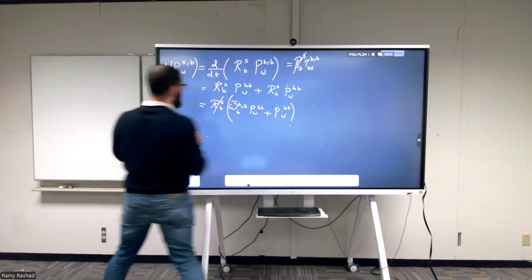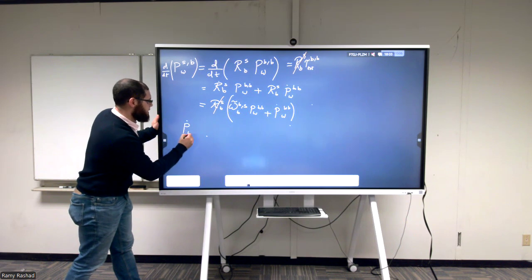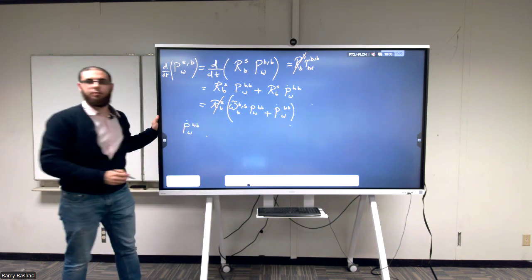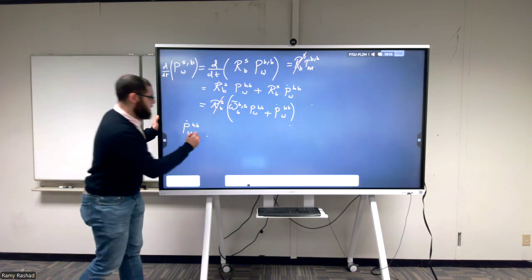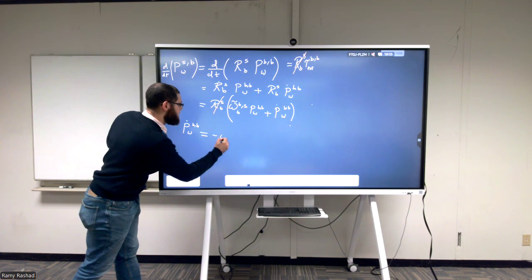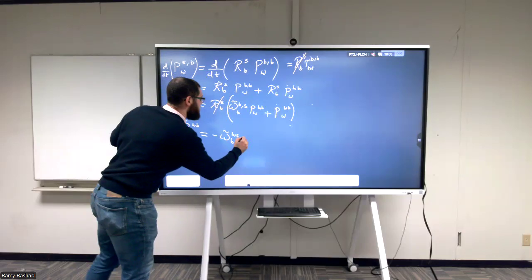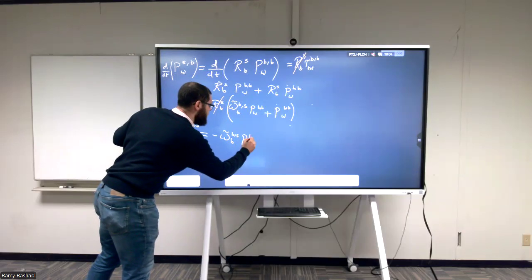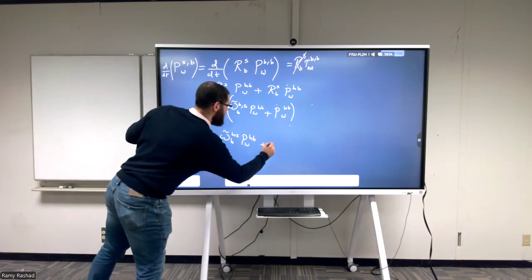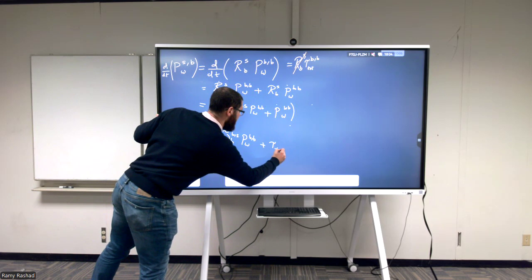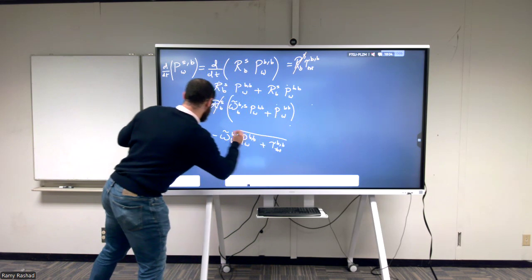the Euler's law is given by the following equation that I'm going to just rewrite: the rate of change of angular momentum seen in the body frame is equal to minus omega tilde multiplied by the angular momentum seen in the body frame plus all of the torques that are applied on the rigid body to make it rotate expressed in the B frame.